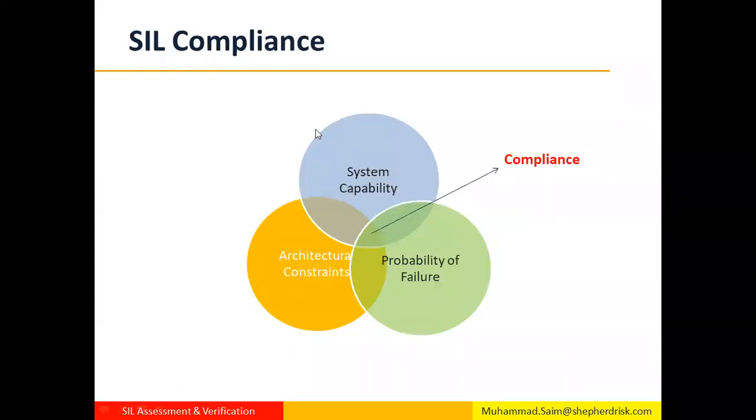Moving ahead, we talked about in STAR that the SIL compliance is about system capability, architectural constraints, and the PFD, probability of failure. So I'll touch a little bit on architectural constraints to strengthen our point of view on 1 out of 2 ESD valves.